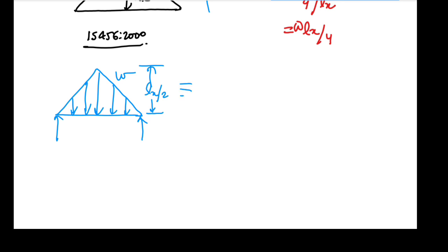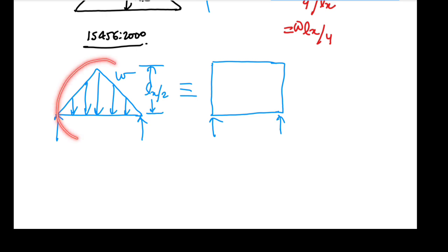We have to imagine an equivalent beam with the same width but rectangular in dimensions. We are imagining that the load intensity effect on the beam because of this loading is equivalent to the load intensity because of this distribution. So we have to find an equivalent load on this beam. This is the load intensity, and the width of the slab is the same, Lx by 2.